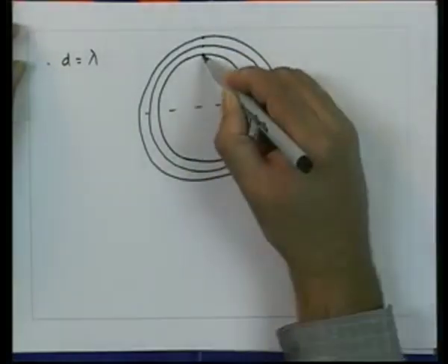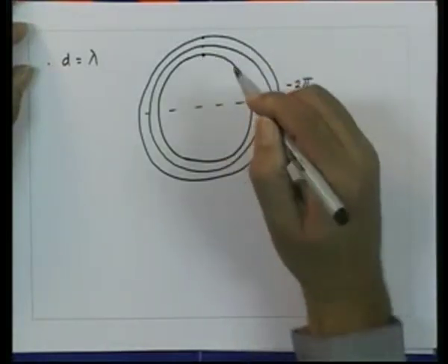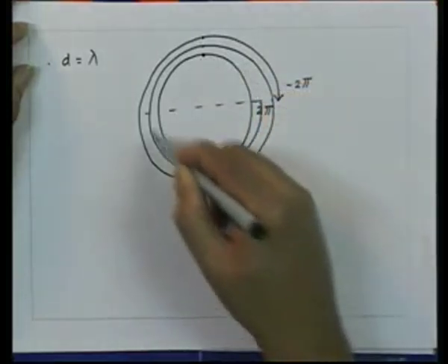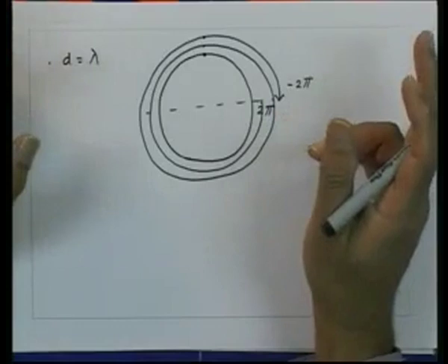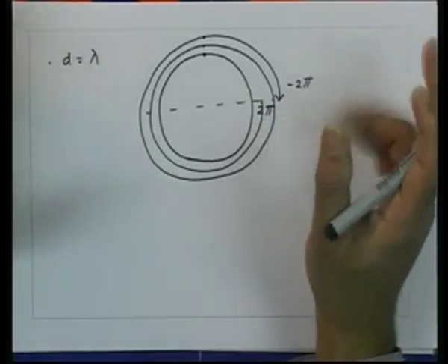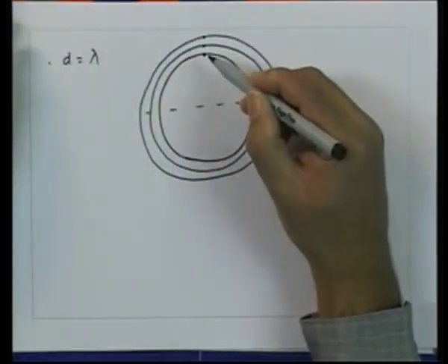So for a given null on the unit circle, we now have two psi values, because the visible range of psi overlaps with itself. But two different values of psi correspond to two different angles in physical space, two different angles phi. What that means is, if I try to put a null corresponding to this value of psi, automatically there will be a null placed in the direction which corresponds to this value of psi.